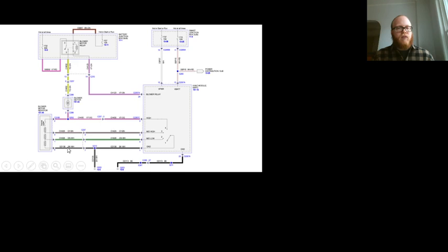All 3 resistors drop parts of the voltage, so at this point we're down to like 9 or 10 volts probably left for the blower motor, and way less current flow going through it as well. So less wattage, and if the job that the blower motor is trying to do is spin fast and blow air, then it's going to do less of that.